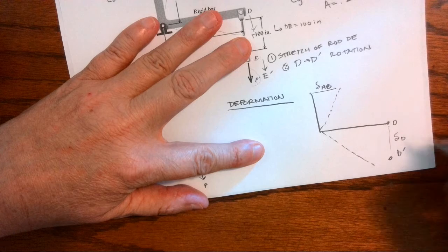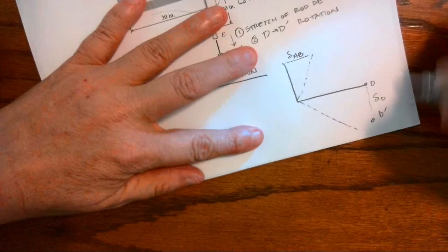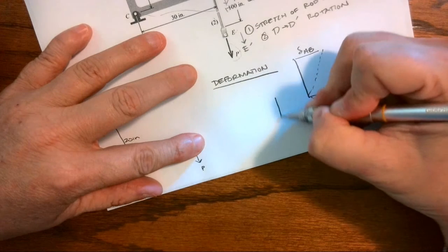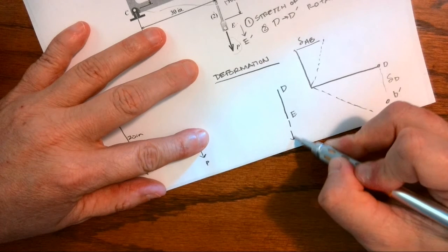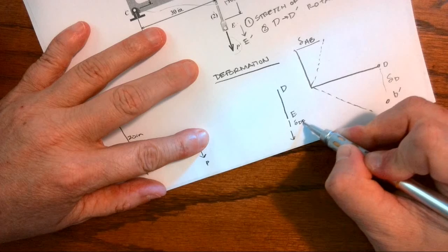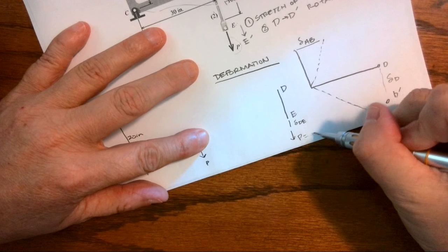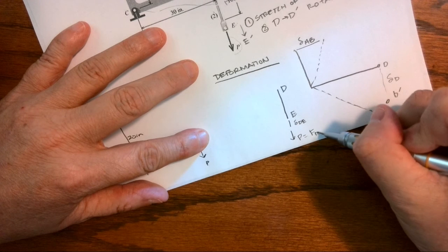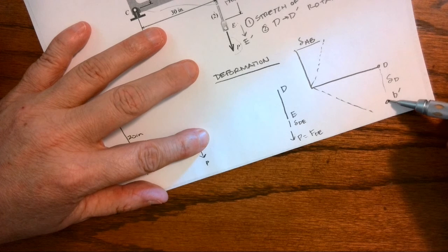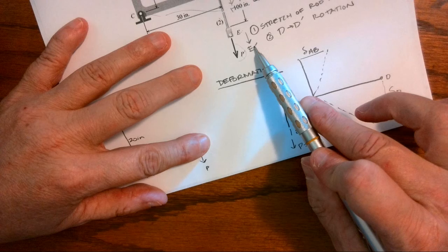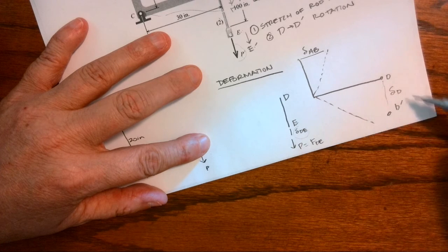We're going to just call that delta D. As I load my cable, so here is cable DE, I know that as I load that, I'm also going to have a delta D to E that's caused by this force P, which is going to equal that force that's in my cable DE. Okay, so as I'm looking at E prime, my final position, it's going to come from both the delta due to the load and the delta from rotation of my system.